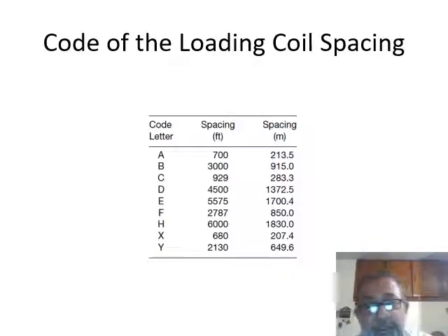And you can see in other code letters, for example in E, you have to place the loading coil every 5,575 feet, right? And in the Y case, we have to place a loading coil after every 2,130 feet, or 649.6 meters.